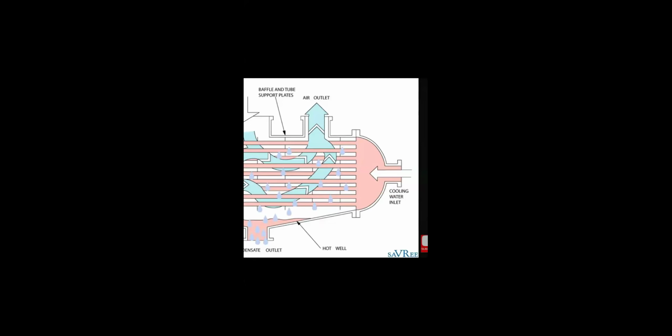Because, sir, it is related to thermal shock. If we flow from the bottom and the coolant is coming from the top, it will get more time for heat exchange, and the temperature difference will not be that much. If we put parallel flow, and suppose the medium temperature is 80 degrees and the coolant temperature is 50, then there will be a temperature deviation that can cause thermal expansion of the plate.